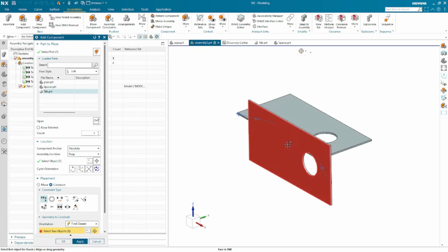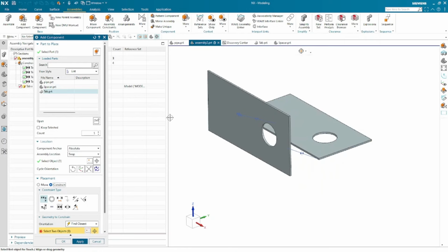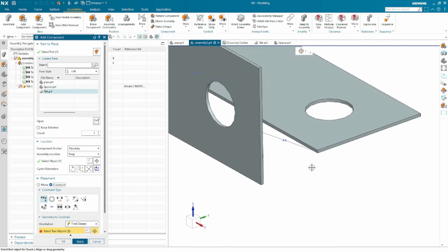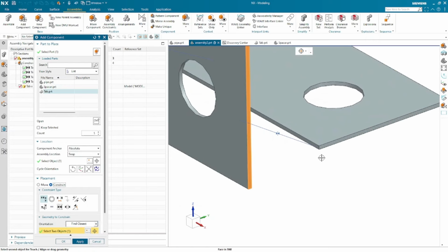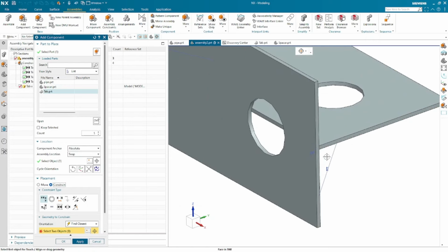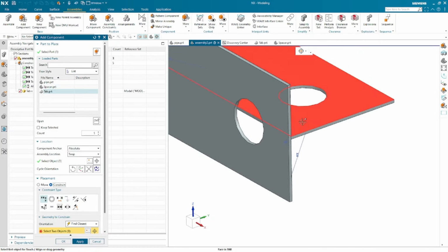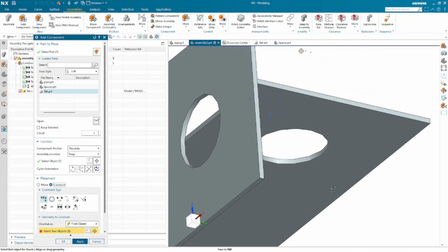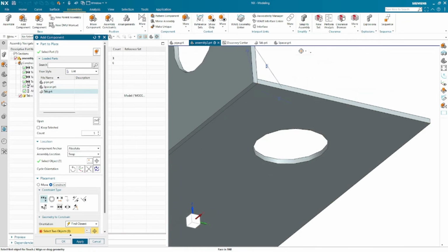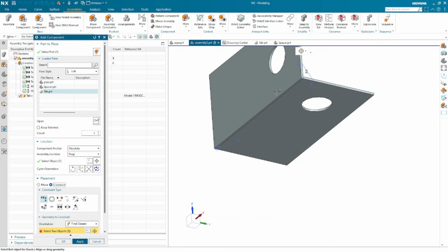So I will assemble all the other parts that I add later, dependent on the first part. We can also freeze the direction x by using these two faces. I'm not switching command, I'm using the same constraint. By just keeping on selecting multiple selections, it goes on with the next constraint. You can see the constraints are being added.